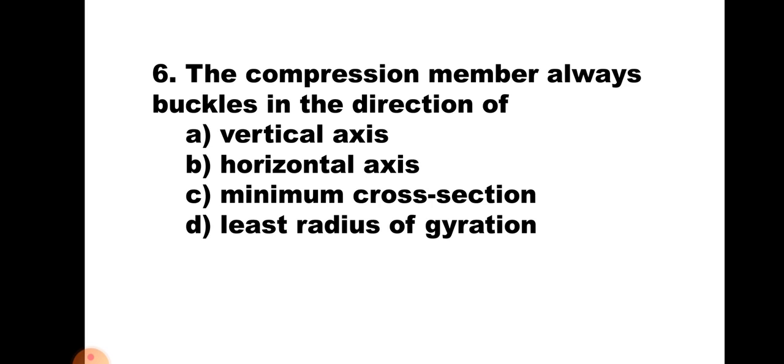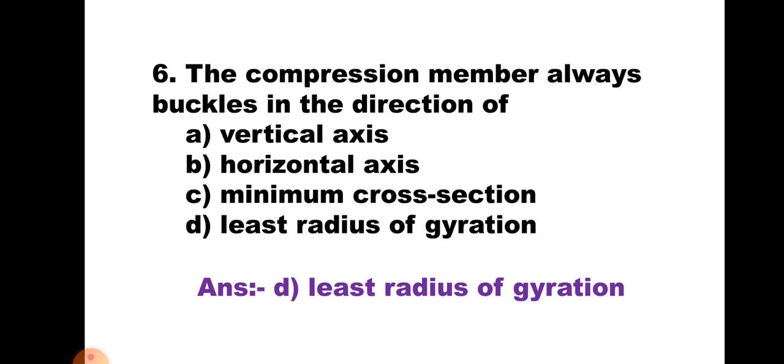So definitely it will be along the axis or in the direction of least radius of gyration. Hence correct answer is D, least radius of gyration.